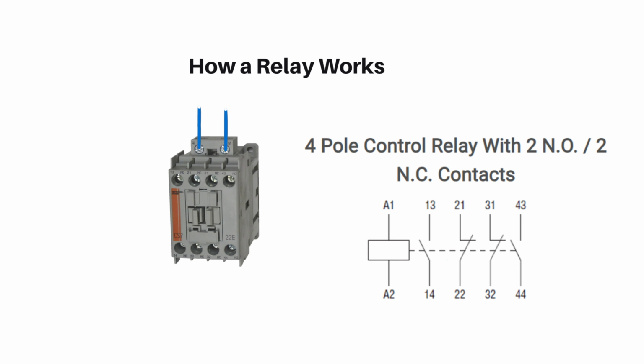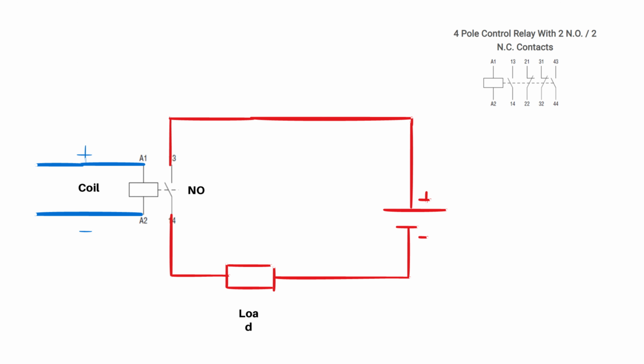Okay, so this is a simple schematic. You can have your load, shown there, which is supplied by a power supply. But you see that we have an NO contact, which means the load will not start because the circuit is not closed, it's open.